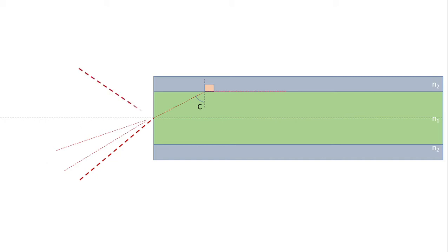Similarly, by symmetry, we can consider another reference pathway as shown, which makes critical angle at the core cladding interface. Light has to enter into the OFC between the two reference pathways to undergo multiple total internal reflections so as to be useful for communication. This representational figure is in two-dimensional plane. When we consider the three-dimensional scenario, this triangular section forms a conical section.